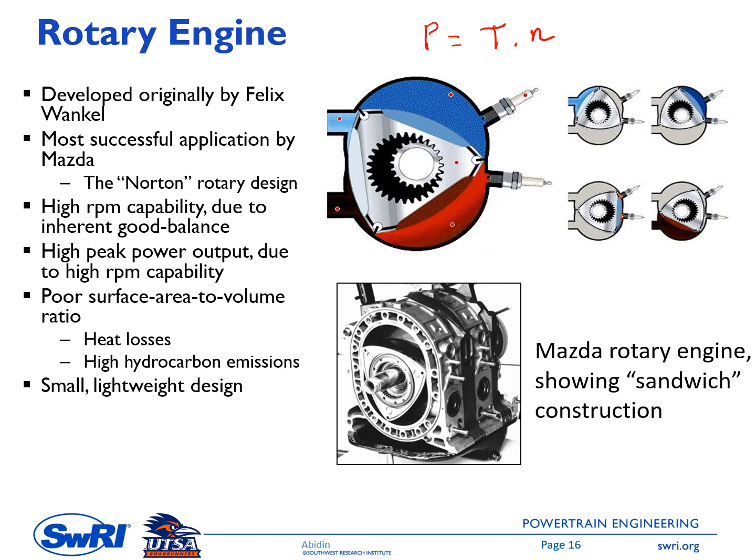The disadvantage of this rotary engine is its poor surface area to volume ratio. That means you will have higher wall heat transfer losses through the chamber wall. It also has higher hydrocarbon emissions because of the leak challenge here. So you need a good sealing for this rotary engine, between the rotor and housing, as well as the rotor apex and the housing. But it's compact, and it can also have a lightweight design.